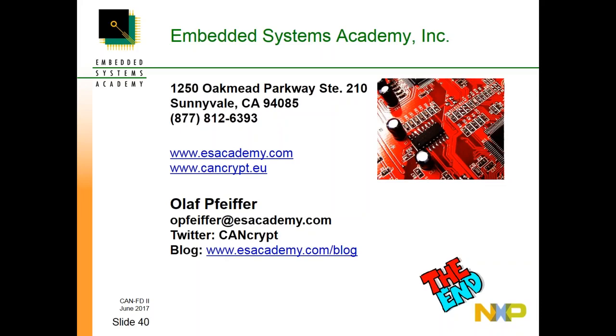But briefly, the question came in about applying these kind of methods to over-the-air updates. There's really nothing here that wouldn't apply as well to an over-the-air update versus a wired update, right? It's just a question of how the infrastructure of the system is designed, correct? Correct. Of course, we have to know that on the lowest end, we'll always have CAN and CAN-FD communication, but how the code file gets to this host that connects there, it could also be a complete remote process.